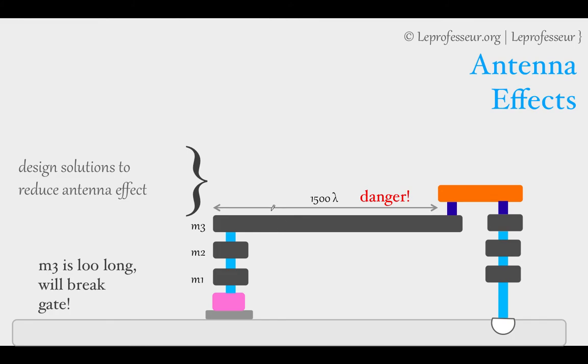Now when we put the jumper, we might end up with problems that the circuit is not routable anymore, because you are creating a dog leg. You are breaking the wire and connecting at a different layer, so you are basically making a dog leg here. And dog legs, if you know a little bit about routing, create problems during the routing.